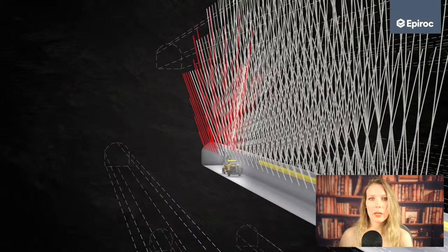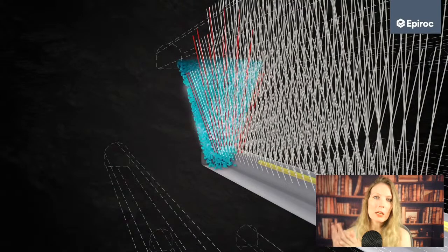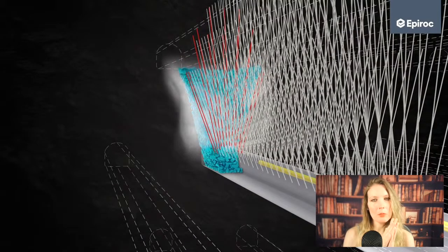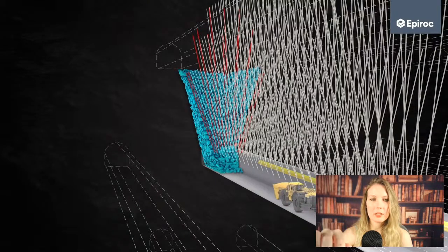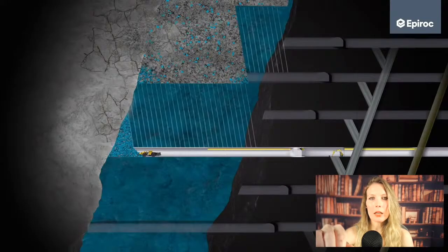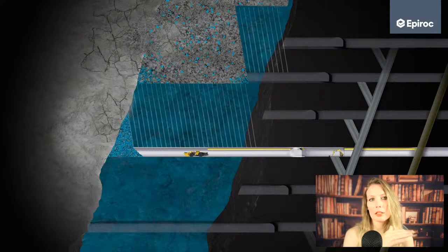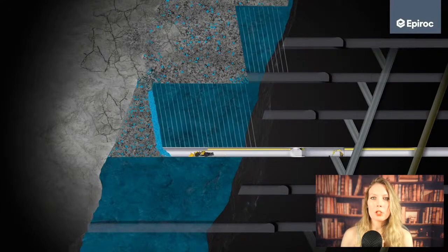a continuous mining cycle. The placement of backfill must be carefully timed to allow adjacent stopes to be mined without compromising stability. For instance, in cut and fill mining, stopes are often extracted in a staggered sequence with the backfill placed immediately after ore removal. If backfill curing times are not considered, adjacent stope extraction may be delayed, slowing down production.